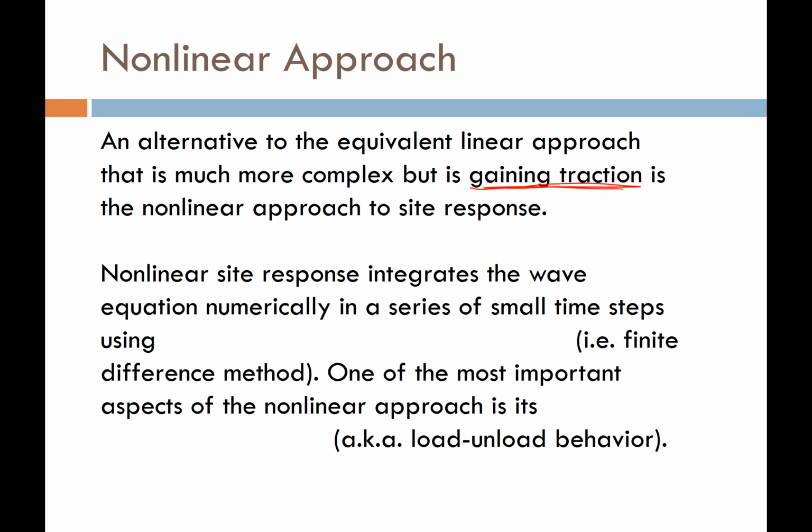This approach is called the nonlinear site response approach, and what this does is we're going to actually integrate and solve that big nasty wave equation. And we're going to integrate it and solve it numerically in a series of small time steps, little delta t's, using a lot of different methods.